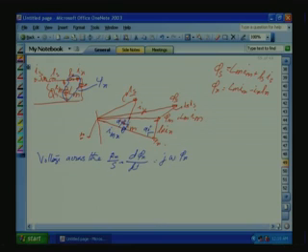So, IS originally defined as IM plus IR can also be defined as a vector sum with the current IMR, which is responsible for psi r, because all these fluxes are produced by the components of IS, where the air gap flux or the air gap plus the stator leakage, that is the psi s or psi r. So, flux is proportional to the current.